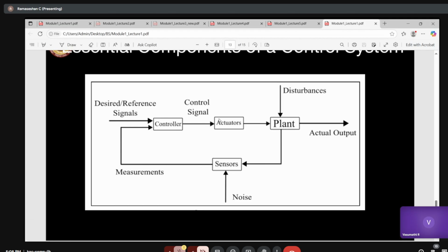No, the actuator is basically a voltage. That's the actuation signal, basically voltage to the motor. The actuator's input is what you set on your keyboard, whatever you are doing to give the voltage. If you are using a rheostat to adjust the voltage, then the actuator input will be the rheostat position. So the control signal of the actuator will be something that you can actually play with. Got it? Yes, got it.